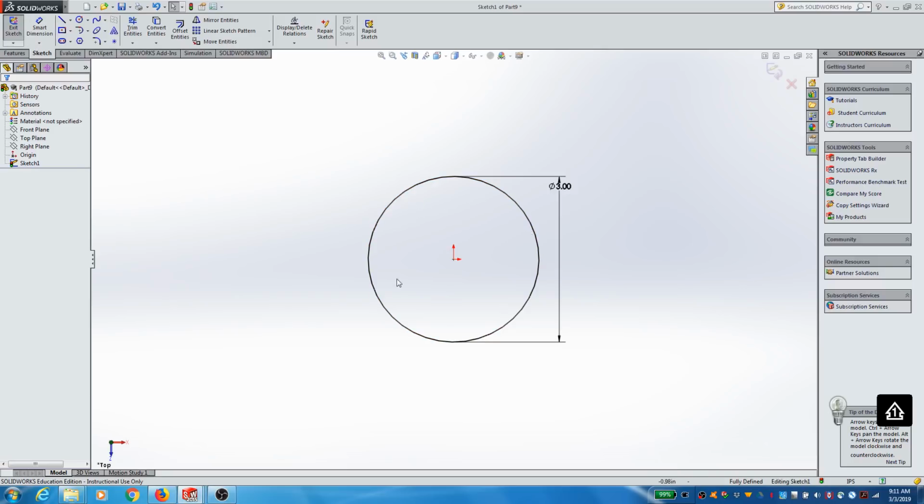What I want to do with this is basically make a plate that's got some holes in it that follow a circular pattern. This is very common in mechanical engineering. A lot of times you have these adapter plates or flanges that you need to fit 2 pipes together, and you're going to have plates mating up with plates using a circular pattern. That's called a bolt circle, and we'll talk about that a little bit more when we get into dimensioning, but bolt circles are super common.